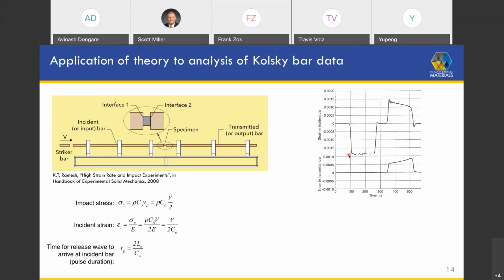Okay, so basically you have explained to me the strain rate with different values of strain rate and time with various deformation mechanisms. Yep. And with the strain rate becoming higher and higher, there's a plateau for stress because of the limit for the dislocation to move.